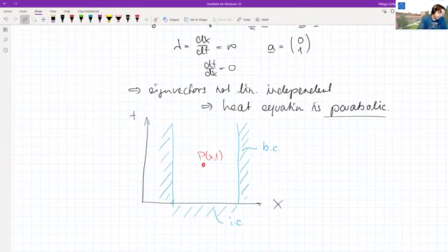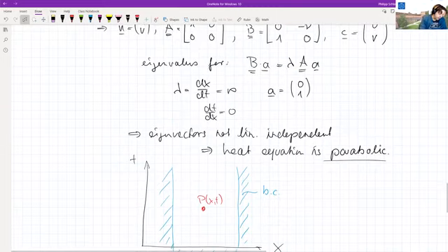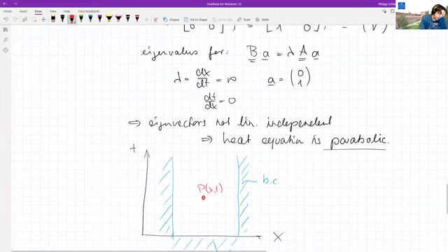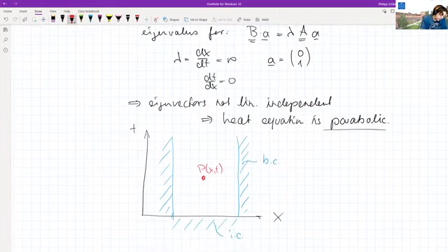And it turns out, if we just look here, dx over dt is infinity. So that means that the characteristics would look like a horizontal line. So this would be the characteristics in this case. And of course, that's exactly in the same way as we also discussed with the Prandtl-Glauert case.